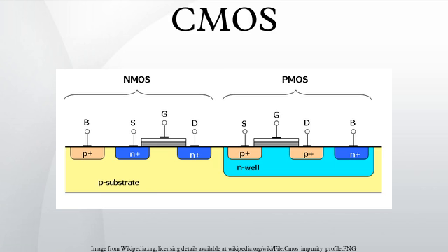Tunneling current becomes very important for transistors below 130 nm technology with gate oxides of 20 Å or thinner. Leakage current through reverse bias diodes: small reverse leakage currents are formed due to formation of reverse bias between diffusion regions and wells and substrate. In modern processes, diode leakage is very small compared to sub-threshold and tunneling currents, so these may be neglected during power calculations.